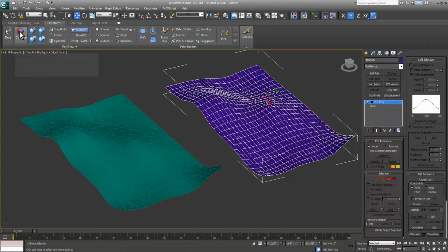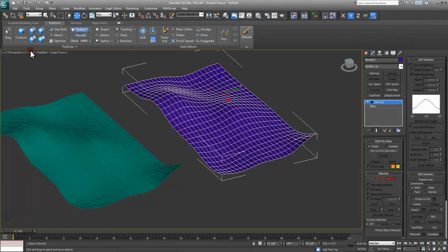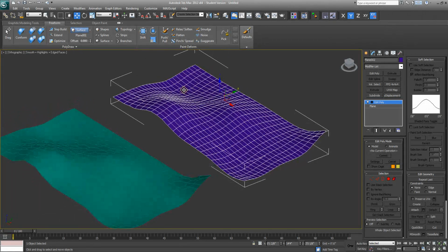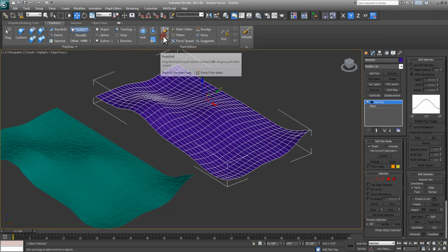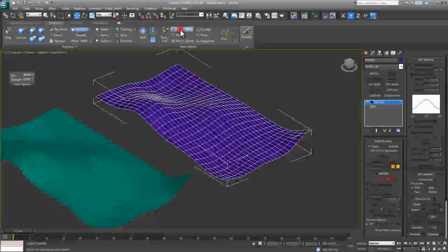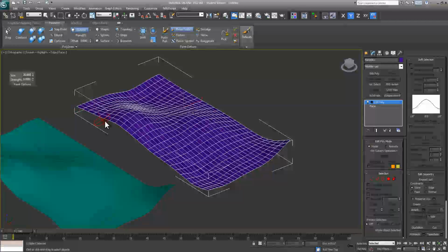just a handy little tool if you're going into the Freeform tab here. And what you can also do, if I want to take this and further modify it, there's push-pull within it. There's also relax and soften. So if I go into my relax and soften, I can adjust the size and the strength and begin to smooth some of this stuff out so it's not as rough or rigid, so that edge becomes a little bit smoother in here.